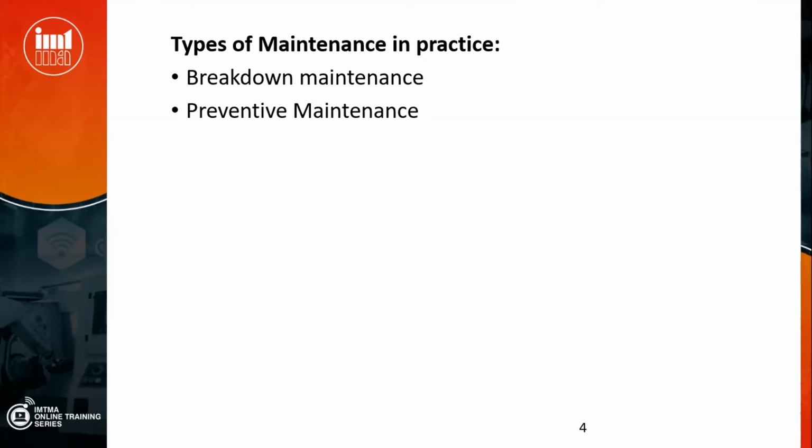But here in preventive maintenance, we had one problem. You have a checklist every week or every month. For example, every month you have to check certain 10 items A, B, C, D. So whether the machine is in working condition or not, you purposely idle the machine, take it for maintenance, and check these 10 items as per the checklist. The machine would have worked for another 10 days or 15 days or a month or even much more. But still, because of your preventive maintenance program, you are intentionally idling the machine.